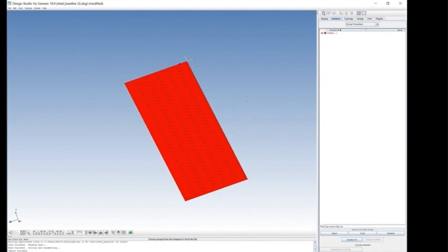We are going to assume that each layer of prepreg is 0.2 millimeters, and we're going to assume that there's 5 plies at minus 90, i.e. laterally along the structure, 5 plies at minus 45, 5 plies at 0, 5 plies at 45, and then 5 plies at 90. So there's going to be 5 layers. Each of those layers is going to contain 5 plies. Each ply is 0.2 millimeters. So each layer is going to be 1 millimeter thick.